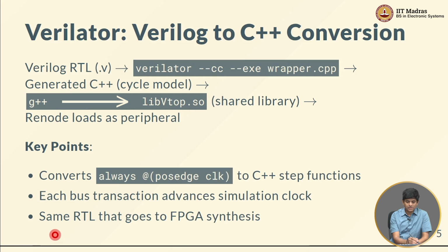And effectively, in other words, it is able to take all your Verilog code, convert it into C++, combine it with some wrapper code that either you write or in some cases it can be generated automatically, and create an executable which you can actually simulate, right? So CocoTB, for example, works very well with Verilator. It's able to generate the wrapper for you. It basically takes in the Python, it takes your Verilog code, does all the things nicely behind the scenes and gets a good simulation going, right?